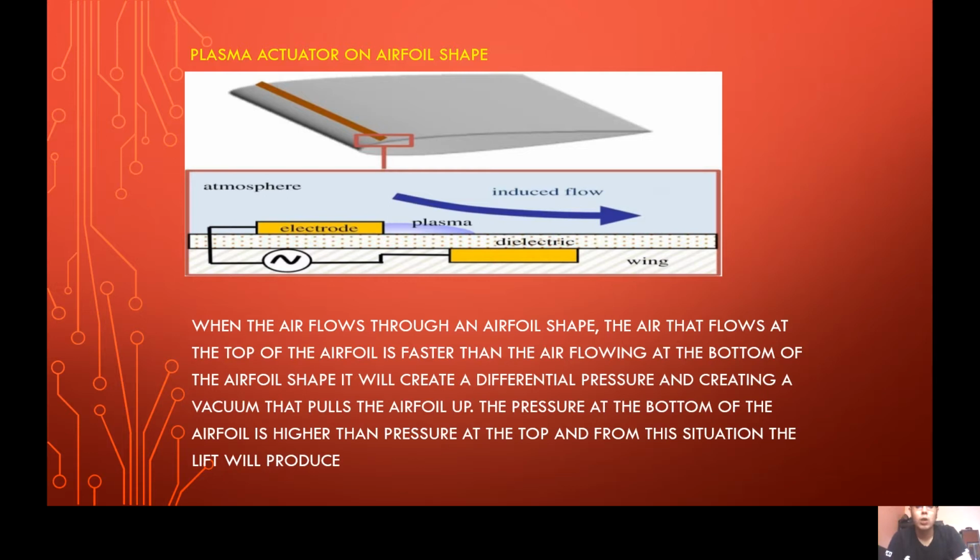When a plasma actuator is installed on both wings and switched on, the electrode will generate an ionized field along the wing area. That will make the airflow accelerate very close to the actuator surface. When this happens, the local airflow is modified and turbulence can be avoided.